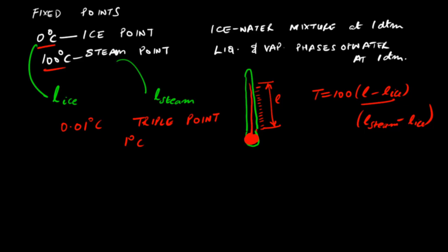Now, what we've seen is that the zeroth law defines that there is something called temperature, a state property, but that temperature we are measuring in terms of other quantities. So the zeroth law does not provide us an absolute scale of temperature. These scales that we've seen, you can define differently, but there exists an absolute scale of temperature that does not depend upon any thermometric substance, and that scale comes from the second law of thermodynamics.